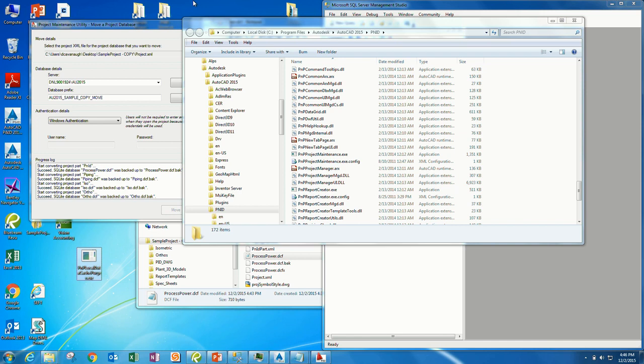I don't know if anybody's experienced trying to tag something where the tag doesn't exist, but it won't let you tag it. I think that's caused by the local data cache, because you might have named something, changed that tag, and then redone this or that. It stores that in the local data cache, so while you have it open, it still thinks that tag exists. That one little click before you open your program every time will really help you out.